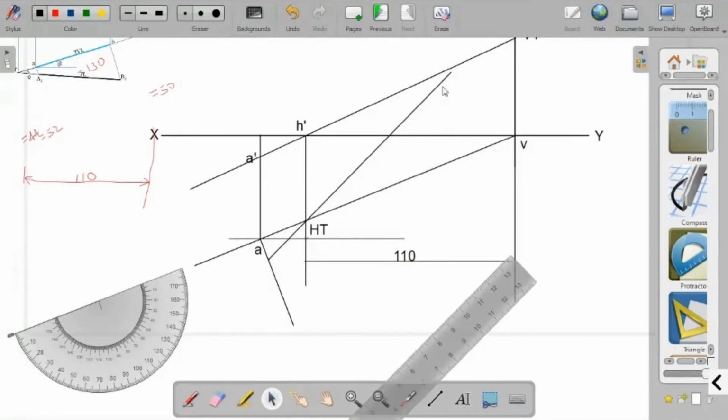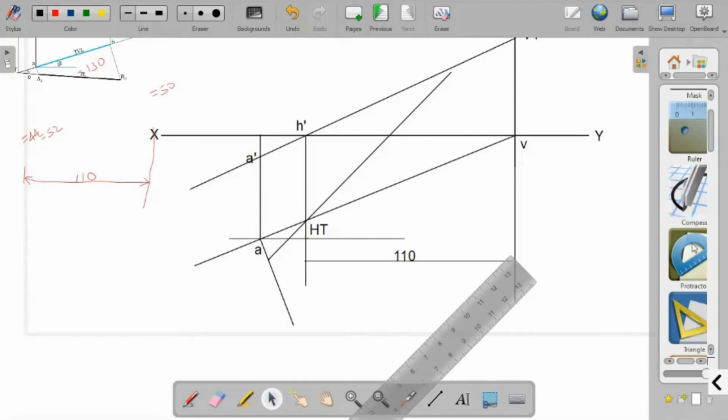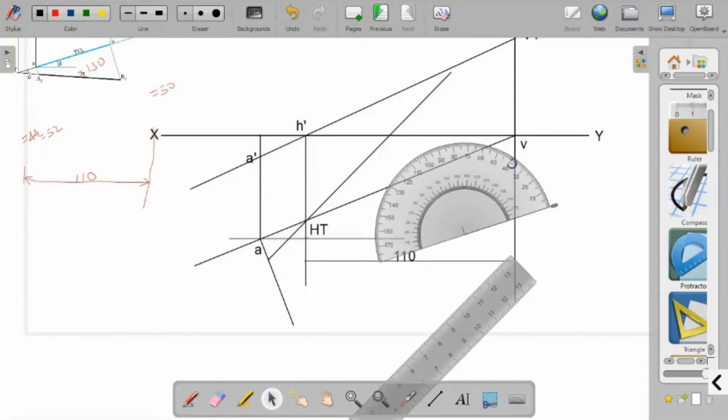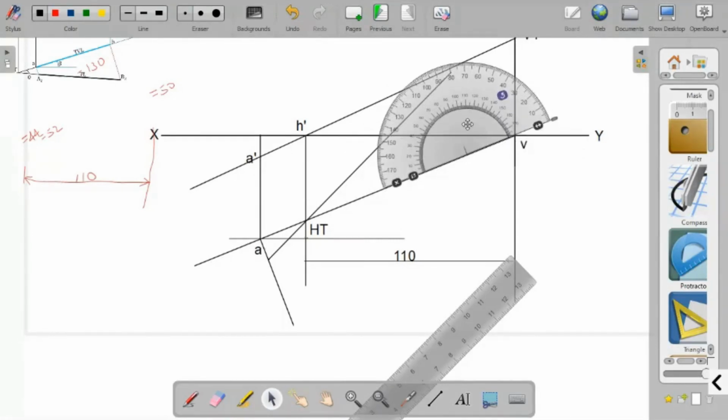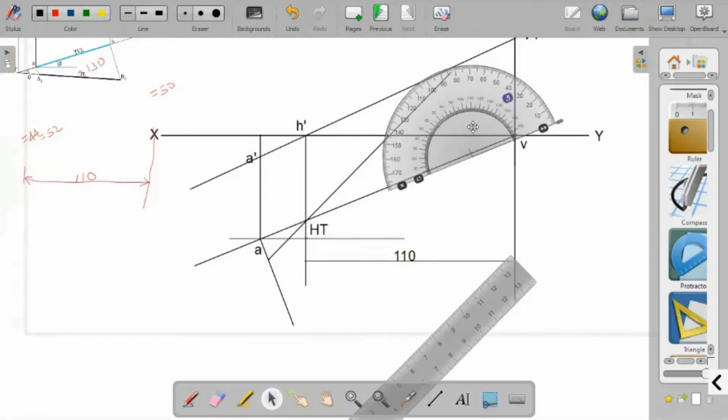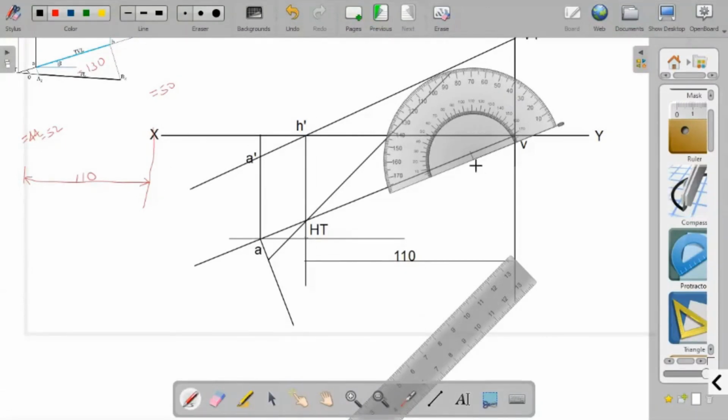perpendicular to this one. Now to draw it there are multiple methods. The method that I am using is not the perfect method, but I have no other option. Otherwise, it is very difficult for me to draw. But when you are using pen and paper, you can use any method. In this method I am not doing it perfectly, but drawing it approximately by moving my protractor through the line, and where it coincides with our perfect line, I mean, the point, I am creating it.